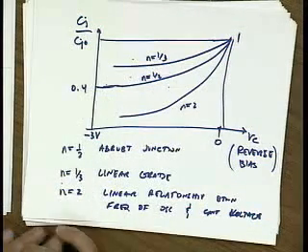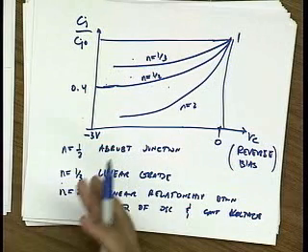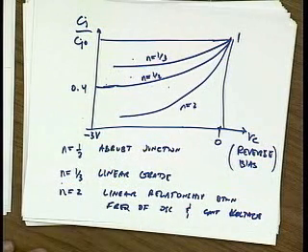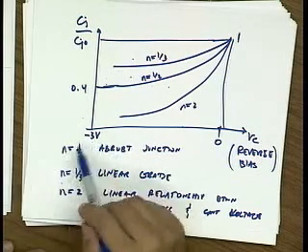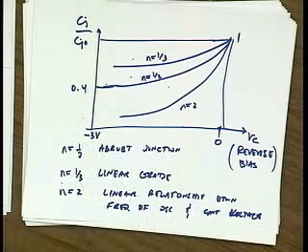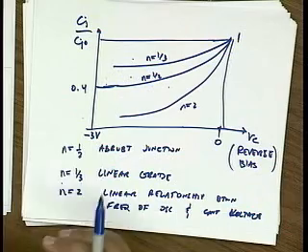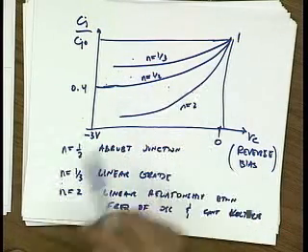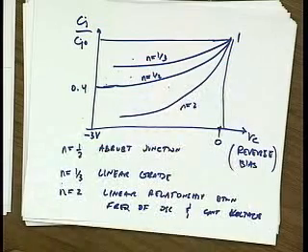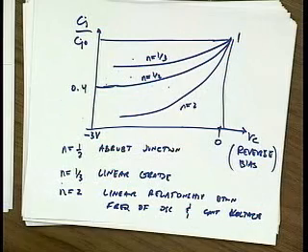So if you go back to what people did in the old days, if they needed more frequency tuning range, if they needed 100% or 50%, what they would do is use even higher voltages, voltages that were even higher than you were allowed to put in the process. And the way they did that was they would have a charge pump circuit somewhere generating a high voltage, and they'd use that voltage only to touch the control node and vary the capacitance. Okay, obviously that's really inconvenient. If you can avoid doing that, you'd like to avoid it.